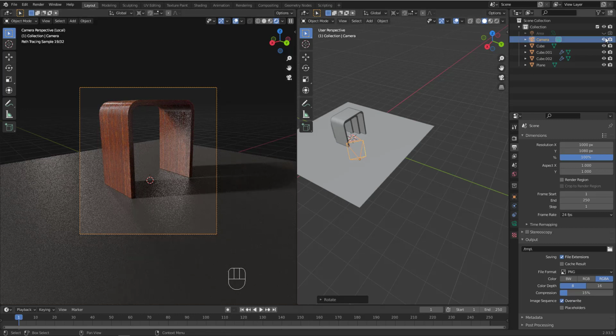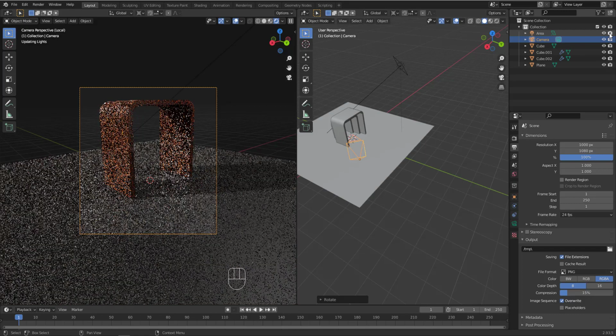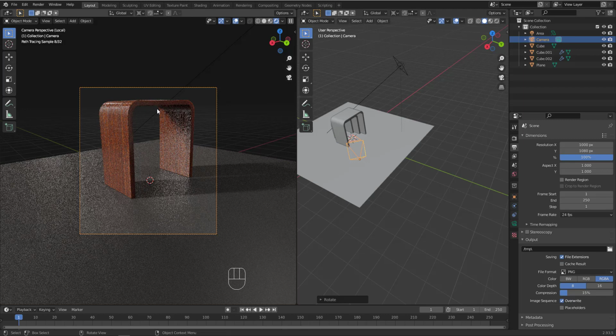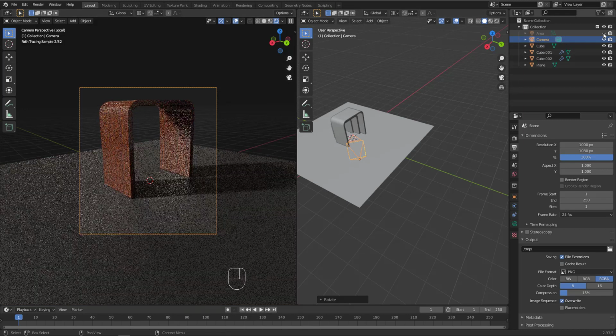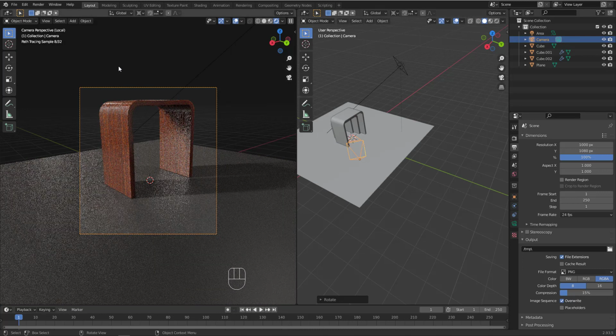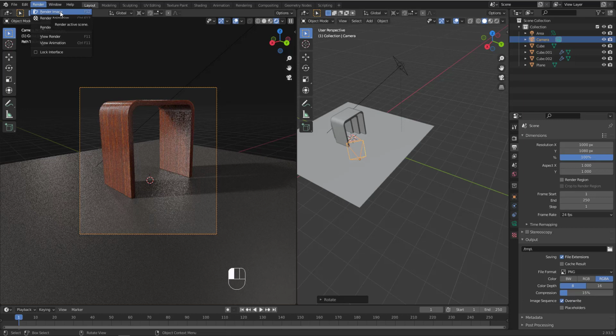And by the way, I can activate the light side by side with the HDRI image if I want extra lighting. I have this option. I can keep it on or off. For me, I will keep it on, and I will go to render and hit render image, or you can hit F12 to achieve this. When the render is finished, I will be back.